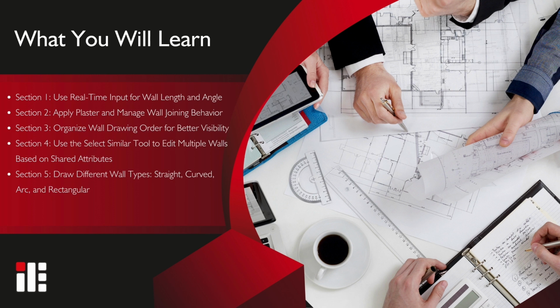In this video, you'll learn how to draw and edit walls in ideCAD Architectural, one of the core steps in building design. We'll show you how to set wall thickness, height, elevation, and materials, and how to place walls precisely using snap points, angle and length input, and reference edge control with the spacebar. You'll also learn how to join walls cleanly, display plaster layers, and split intersecting walls using the trim extend wall